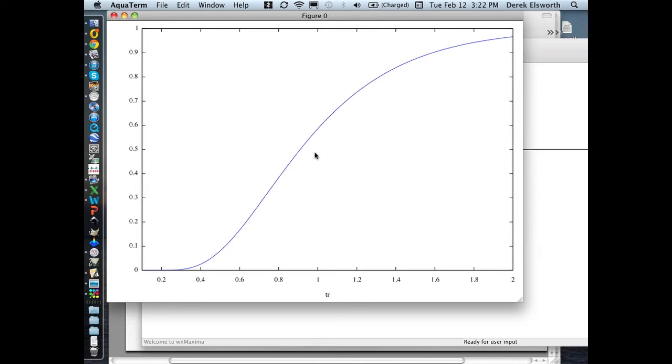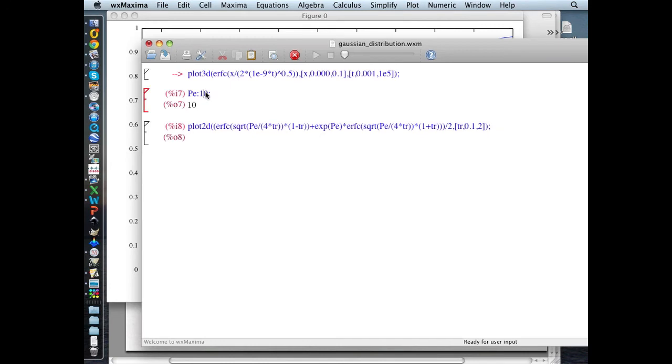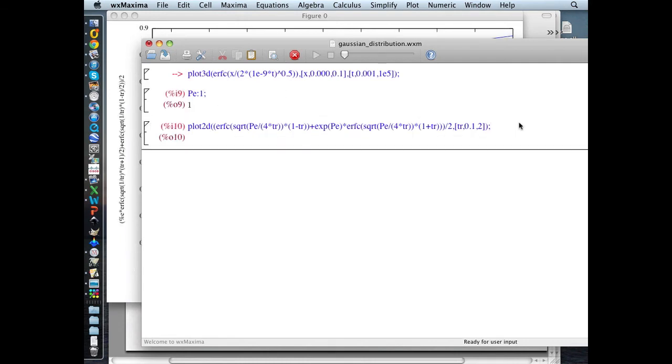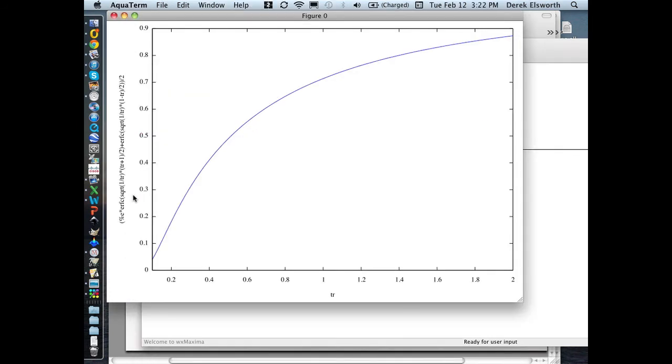So physically, what does that mean? It means that if you're expecting that the main plume arrives only after one pore volume has come through your sample, through your aquifer, then you'll be surprised because it got there earlier. And that's a bad thing, right, if you don't want to be surprised. If you look at the case where the Peclet number is equal to 1, where in other words advection and dispersion are roughly the same importance, then you'd be even more surprised if you're basing your calculations on that.